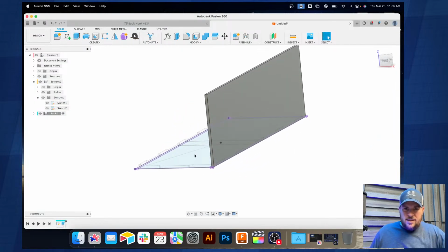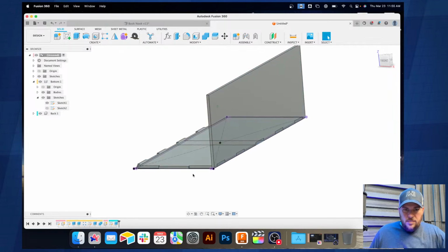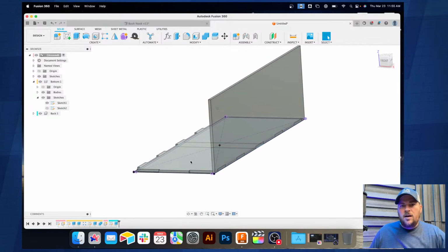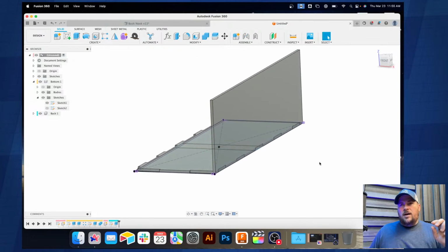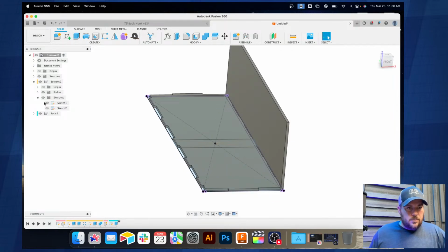And so now I'll go up to the highest level. Because I have these tenons already in here, I can just do the combine tool and cut them away. And then I can add the tolerance, because right now in digital space, those things are completely tangent to each other. But in reality, there's no way that they're going to be able to fit together. So in the course, we created the 3D printing tolerance tester and the laser cut tolerance testers that you can download, cut, and make for this very reason.